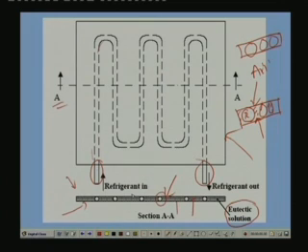In another method, this space is not filled with any solution, but it is evacuated. When you evacuate it, the outside pressure, which is atmospheric, presses these two outer plates. As a result, again good thermal contact is formed between the tubes and the plates, right? But more widely the eutectic solution is used, because the advantage of eutectic solution is that in addition to providing good thermal contact, it also provides what is known as hold up capacity.